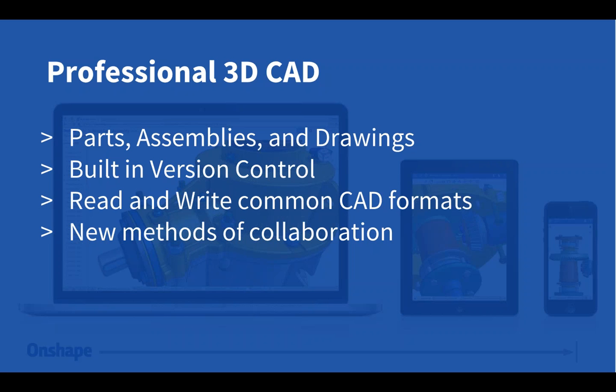A question that's popped up is, what's a version, aka version control? In Onshape, you can think of a version as a snapshot of the document, where it captures everything in the document at that moment, and you can always go back and look at it, maybe download the models at that state. But think of it as a read-only snapshot, something you can't change, of everything in your document: parts, assemblies, drawings, even the miscellaneous data that you may import. So that's what we consider a version.